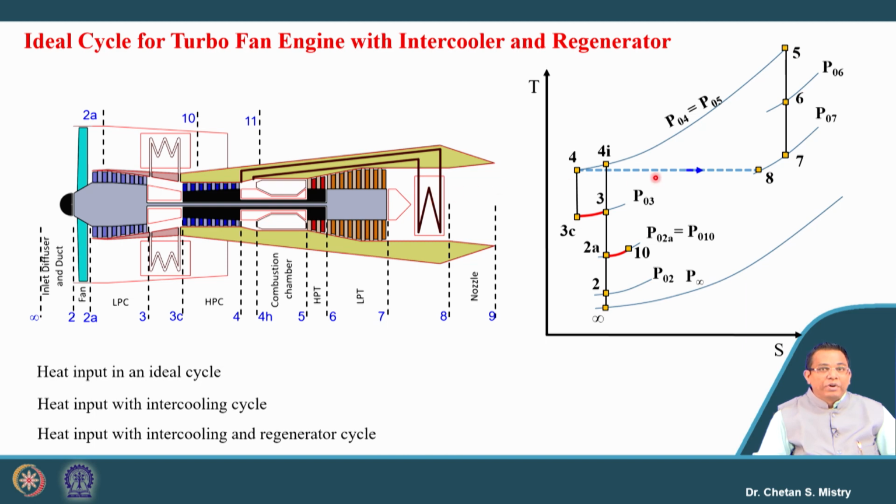So my temperature at the entry of the nozzle will be lower because we have taken away some amount of heat. How have we taken out some amount of heat? Say this is the amount of heat. So what exactly will it be doing? It will be raising the temperature of my air which is coming out from the HP compressor. So here we have a heat exchange process happening.